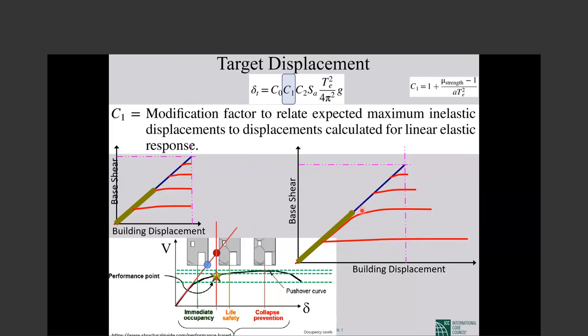If it's less, they call it equal energy. The area under this remains almost constant. So if the strength is at this level, it goes a little bit more because it can then cover the same area as the original. But if you reduce the strength too much, it should go much more so that the area under the curve remains as the initial curve.